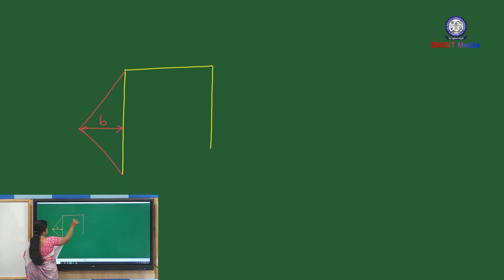That is sagging bending moment, positive bending moment. Now coming to span BC, it is subjected to UDL. For the UDL, the maximum bending moment formula is WL squared by 8. If you substitute, we get a magnitude of 4.5. The shape of the diagram is parabolic because it is subjected to UDL. There is no load on span CD, so no need to calculate the simply supported bending moment because the load is 0.